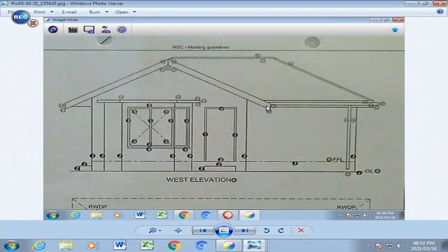In the middle you have the roof structure that's there, and luckily the roof structure is at 30-degree angle, so it makes it easy for us to draw with a set square. Take note of the thickness of the barge boards, which would be 5 millimeters, and also the fascia boards that will be at 5 millimeters here as well. In this case the gutter is drawn 2 millimeter lines apart to indicate the gutter, and it goes slightly 2 millimeter over here, which means it returns on that side there.